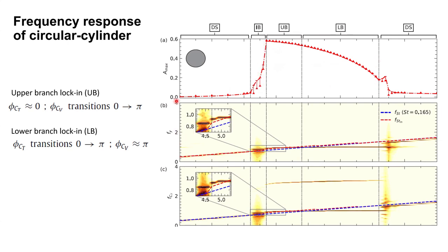Now, in the second panel, I'm plotting frequency contours. Any signal which I get for a particular simulation will give me multiple frequencies. If I do an FFT or discrete Fourier transform of that signal, I'll get several frequencies. Normally, we are interested in the dominating frequency, but the fact is I get so many frequencies. I can actually plot all those frequencies, right? And I have so many values for those frequencies. Now I'm presenting those frequencies by virtue of contours.